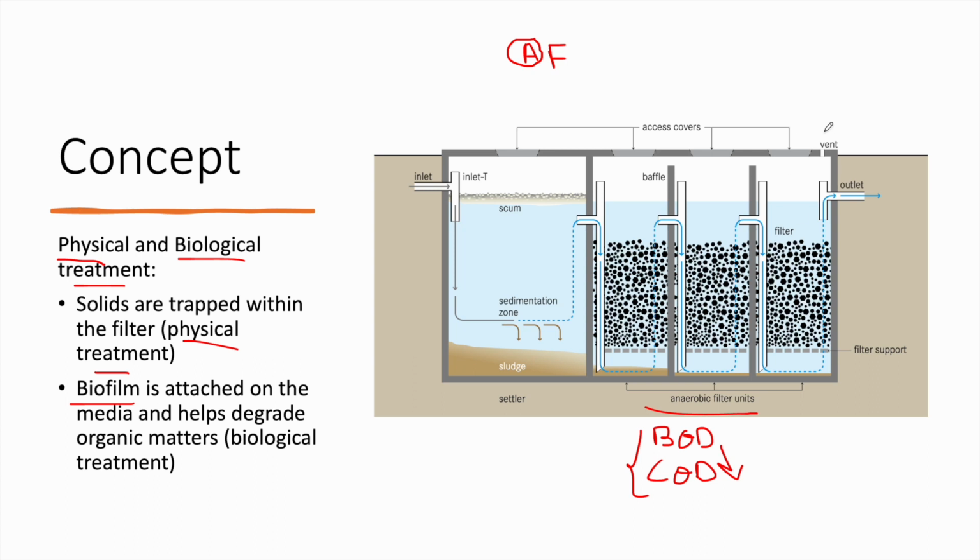Also notice an important component, which is the vent pipe. When we say anaerobic treatment, we might face some bad odors that we really want to avoid. So always pay attention to the vent, to help the odorous gases to escape.